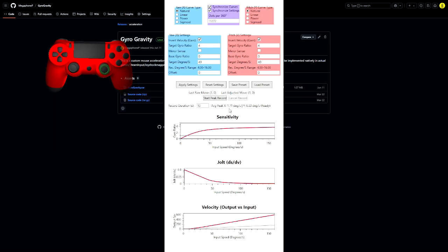So even when you think you're holding your controller perfectly still, there's movement. So the x-axis here seems more accurate, because when I've measured this, I'm usually about around 2 to 3 degrees per second of shakiness from just holding my controller still. And so I'd call that range like your ambient resting point.